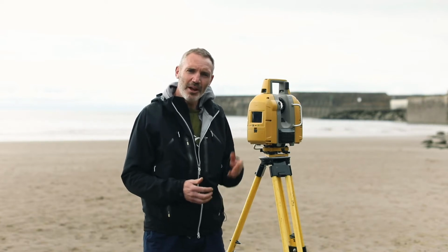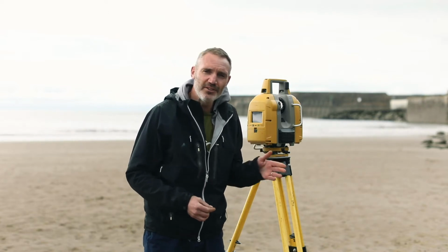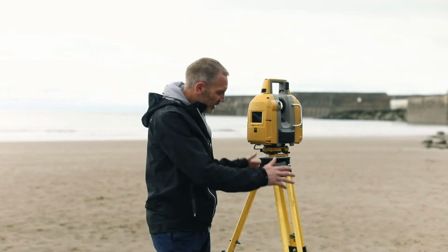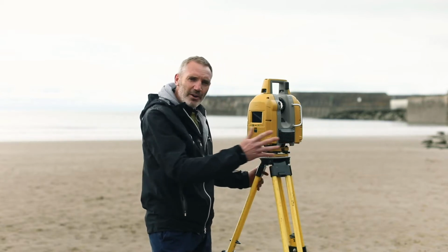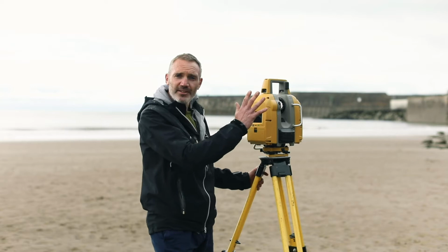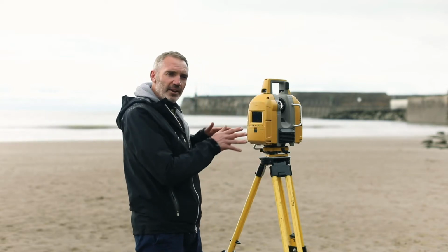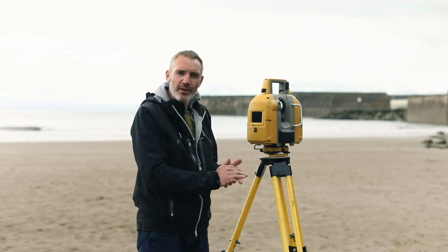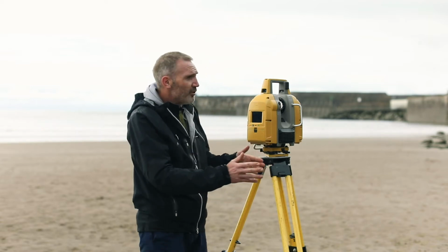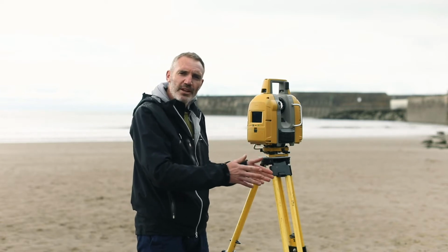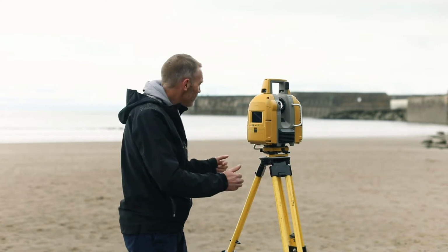3D scanning is an optical survey tool, and what that means is it can only measure what it can see, so we can't see round corners. So the survey method is setting up on one position and acquiring the data in 360 degrees, and then moving on to another location where we get a different perspective on the target that we're mapping. On this sort of survey of a big structure like a seawall, I like to go up maybe 40 or 50 meters between stations.